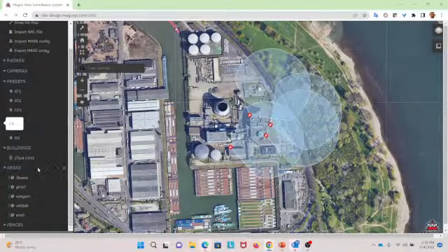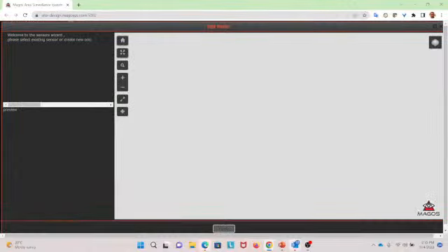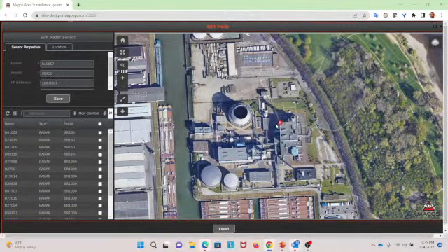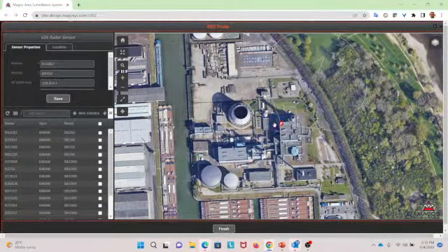Let's do this quickly. Let's grab a radar. Let me see this one. A right click again tells me the name of that radar. So 15.8 something is this one. And here's the delete, here's the edit. Let's go edit. And now I can take it and move it along, or I can use the keyboard as well. As most of you know, using control and the arrow keys moves it by 10 meters. If you keep shift pressed, it moves it by 1 meter.